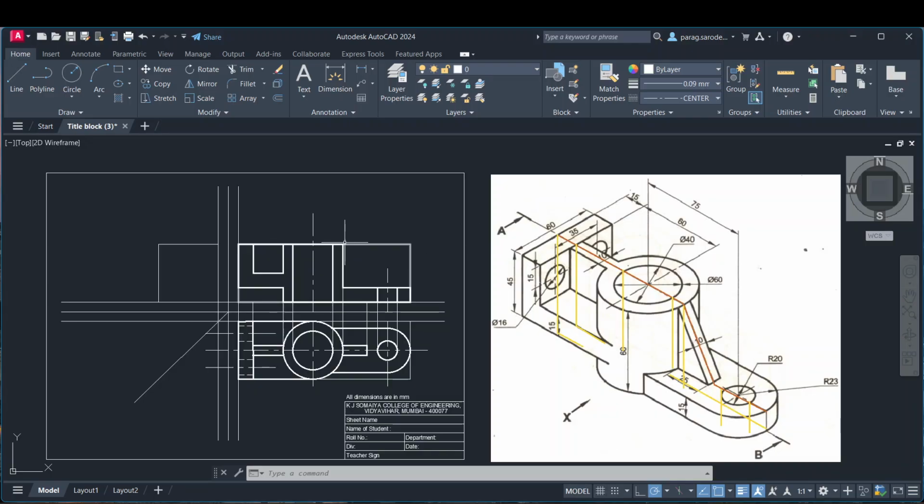So how to show it, right? And what is its position from this edge? Its position is at a distance of 15 mm. So for such cases, if there is a circular hole which needed to be shown by hidden line, we generally omit it. So what we can do, we can just show a center line for it. What is the location? Here it is 15 mm, and in this way we can show it. And then we will proceed for drawing the section.